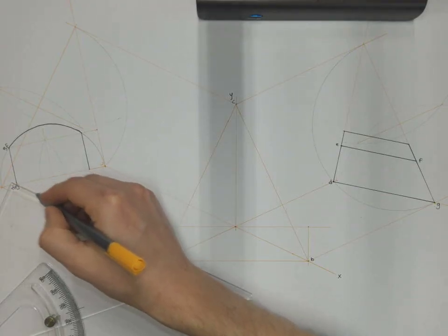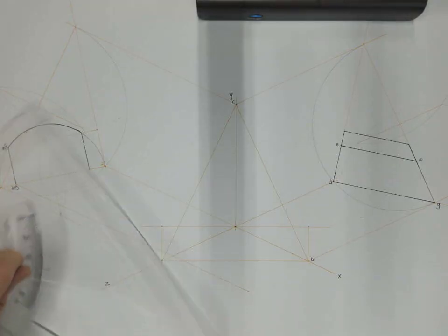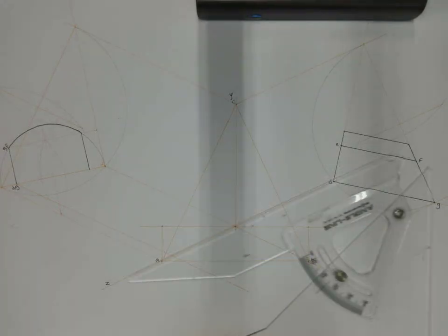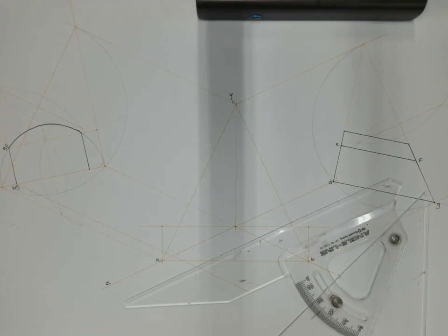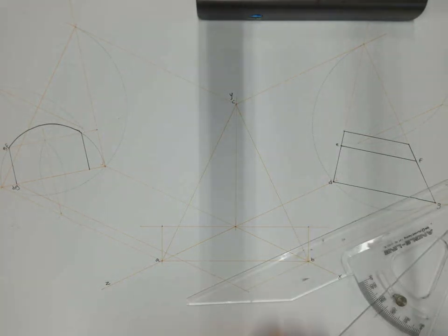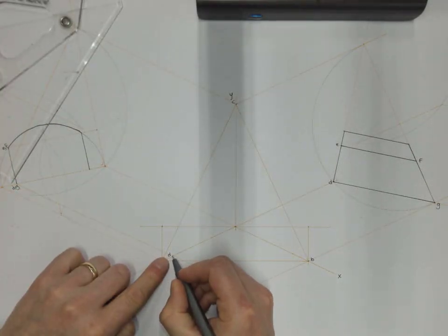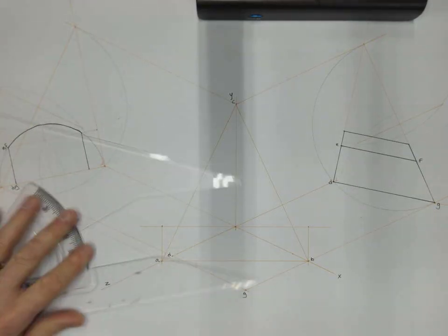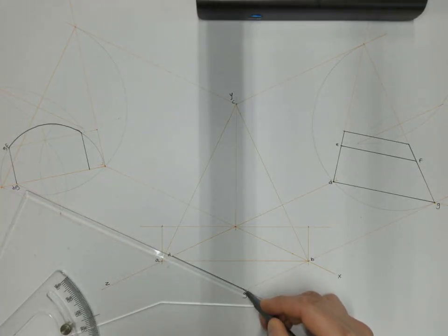So now if I take D, G down parallel to the x-axis, and then from the elevation, well, D is already taken down parallel to the z-axis, so I'm just going to project G down parallel to the z-axis. So there I have the point, if we follow it here, there's the point D, there's the point G. And technically you can harden that in. That is the ground line of that visible surface.